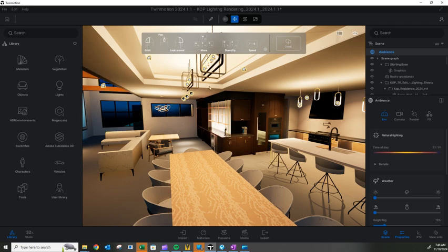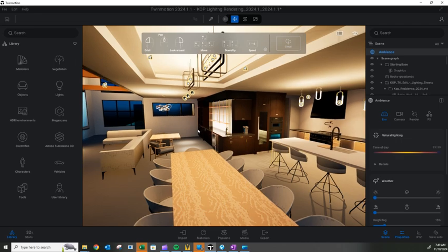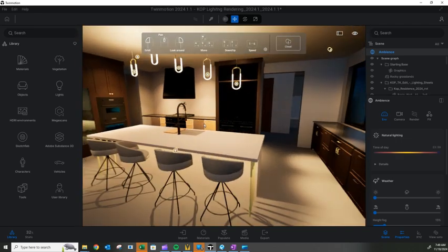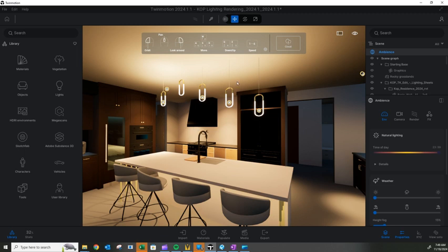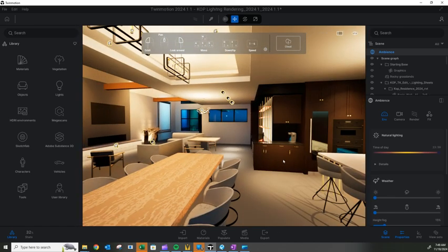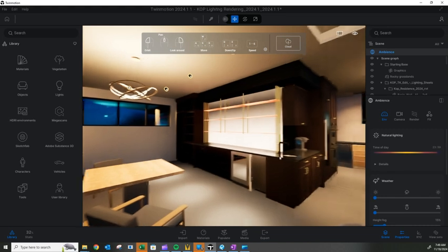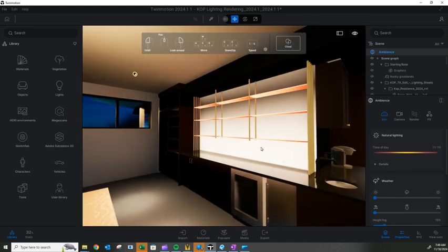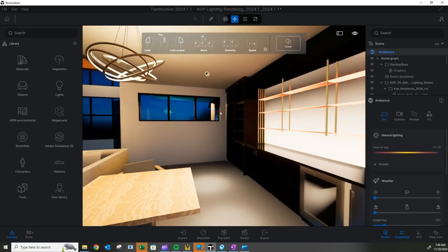And then there's also the decorative lighting, and we locate the decorative lights on the plans, and sometimes we put in a filler in the spec, but ultimately the client or the interior designer picks out that decorative light, what they want to go there. Here we have multi-cluster pendant, just again showing an idea. We have recessed downlights, we have under counter light under the glow, we have 3 pinhole lights over here, bar light, we have LED panel, which they would cut and put a glass over. Same thing in here. RGBW is on the spec, so they can change it.